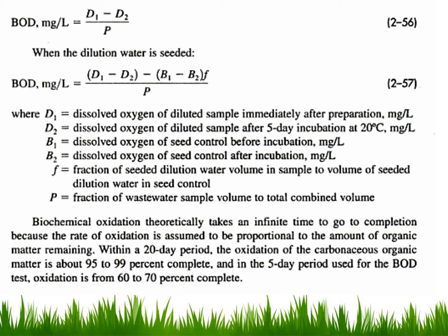Immediately, the answer is that we are only focusing on the carbonaceous BOD, which only deals with the initial 5 days. And after 5 days, the nitrogenous BOD starts its role, and then nitrogen starts decomposing, and then we will be more focused on the overall BOD, and it can lead to a 20 days test.